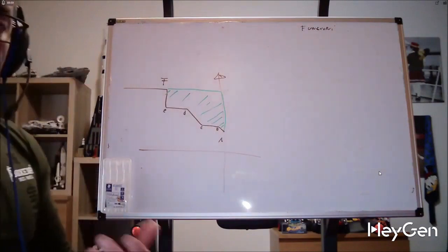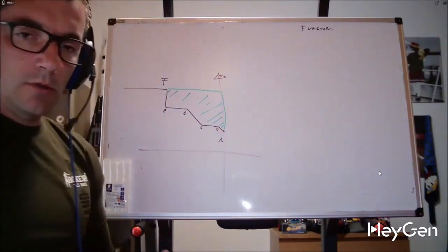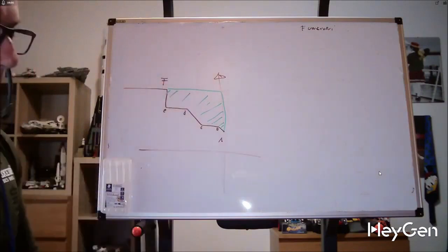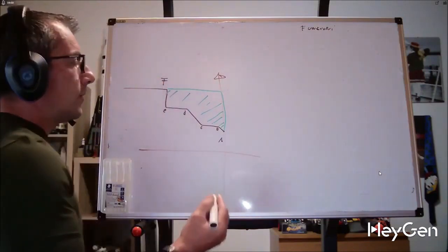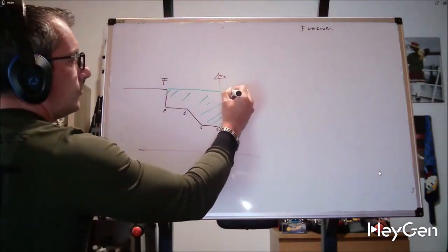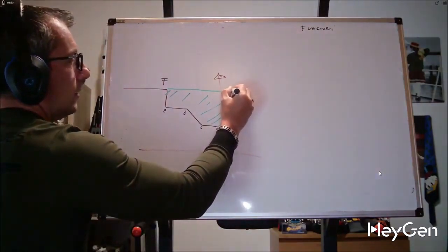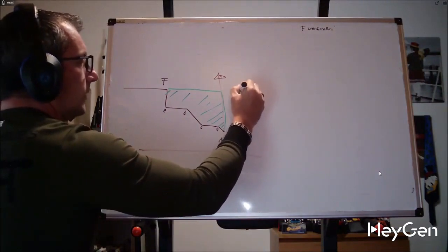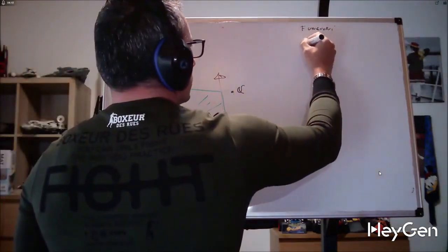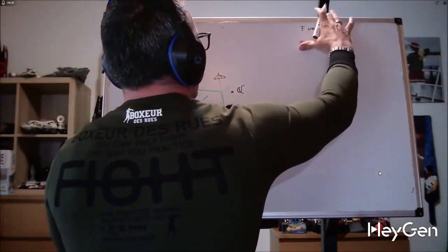So we need to give the machine an idea of the piece, let it know that we're using a macro, and then define the profile on the raw piece. The first thing we should do is position ourselves at this point. Let's call it point alpha.